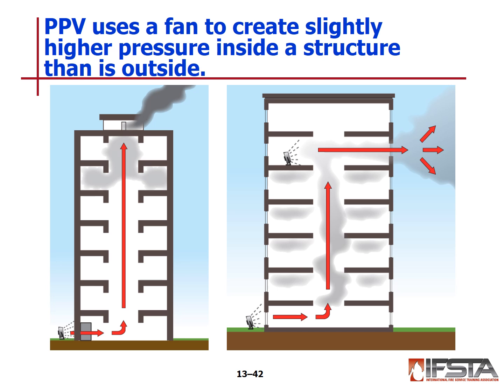Another, more complicated and more coordinated way to do it is when you can't get it to push out the top because of the roof structure. We're trying to get the smoke and heat out, so we open up a window on the leeward side. We set up a positive pressure fan to help force that air out. Then we set up one at the main level at the bottom to push it all up. So it basically gets pushed up, and when it gets to the other fan, that fan pushes it back out.